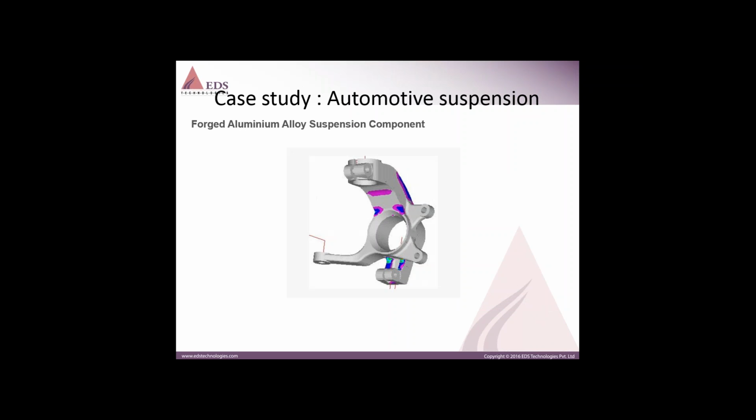And the tested loading cycle, for example one cycle of loading, we will test it and supply it to FESafe, and we will do the scale and combine operation in FESafe. And again, you can see very close correlation between test life and FESafe.